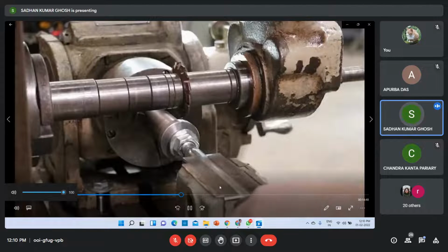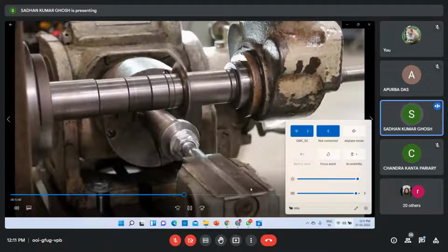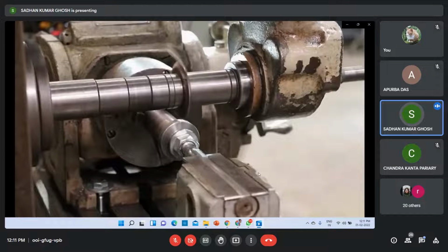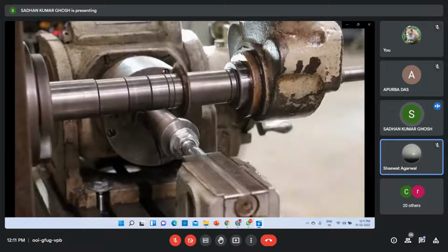This is the method I do. Every time I do this, I have people tell me this isn't the right way of doing it. This method's always worked for me. I know a lot of other shops that use this. And basically, we're just going to find the top of that shaft by finding where it hits out on there. So just eyeballing it, I'm very close to being right in the center. I'm going to raise this up until I just barely start to get a cut on there.